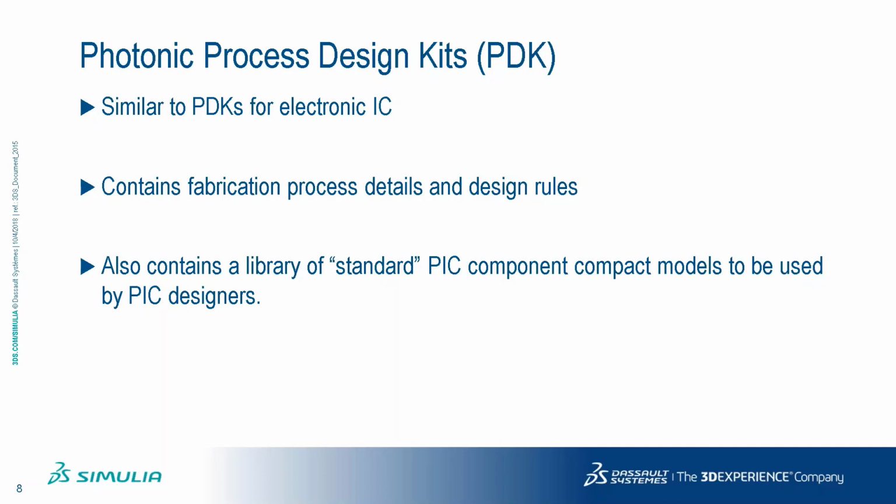So basically, you have your existing design, but now you go to Fab A, B, and C, and depending upon the process that they use to fabricate your circuit, you will actually see that the actual outcome is slightly different, and it depends on the fabrication process. And so the exact process is obviously proprietary, but it is encoded in those process design kits.